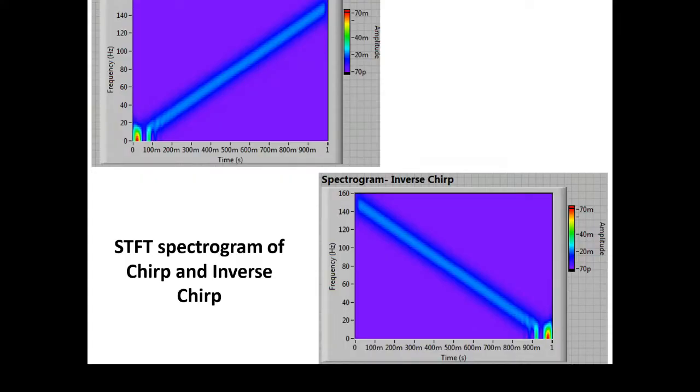Okay, so the first simplest method to gain entry into joint time frequency analysis is the short time Fourier transform. What it says is, suppose you have a signal like this. What should we do? We will fix a window in the time domain. Suppose we take a 10-second window, it may be smaller or larger depending upon your requirement. I take this signal component and perform the Fourier transform.